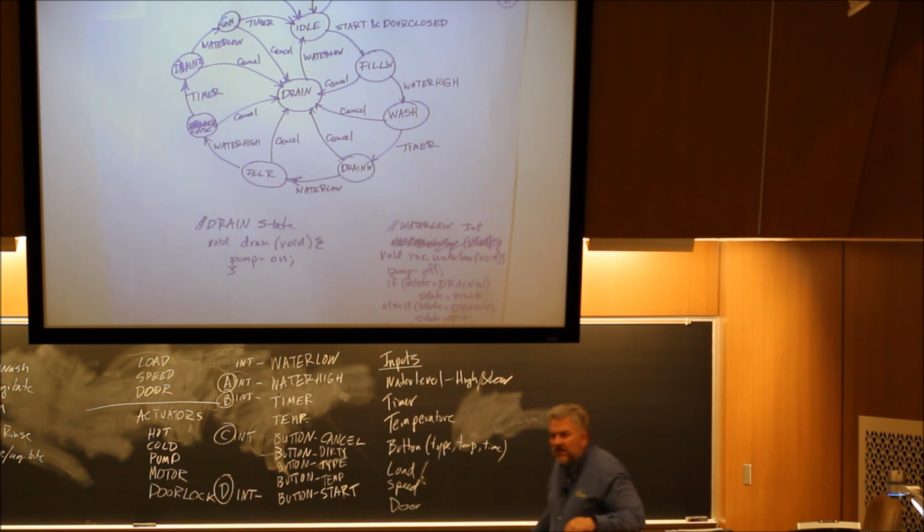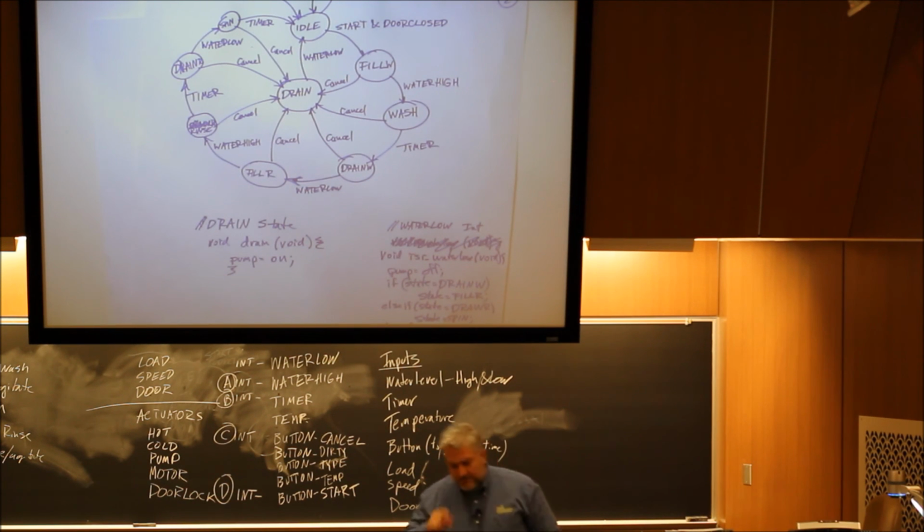Yes? Should the ISR be as small as possible and all timers can be done? Well, think about this. Timer calculate. What you want to do is to avoid doing calculations in an ISR. By setting flags or setting variables, is that taking a lot of time? Yeah, so in the fill function we can calculate the water level that is to be filled. So in the idle we just change the state machine state and we go to that function.